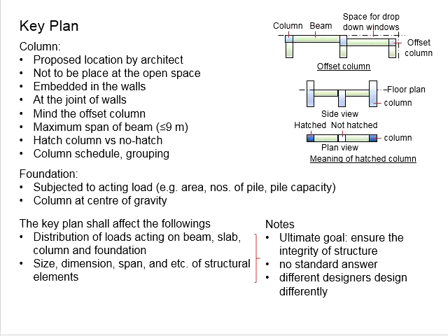However, when you deal with low soil capacity, for example soft soil or peat, you don't have sufficient bearing resistance and your footing size will be unrealistically big. Most likely you will be required to drive piles into the soil until they reach the hard strata underneath the ground. And you will need to consider the total loads taken by the foundations.